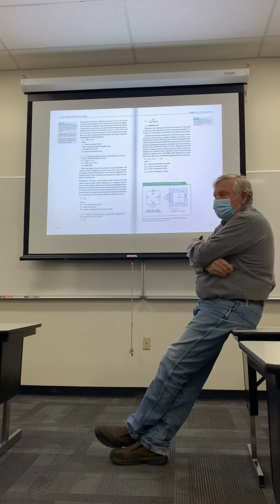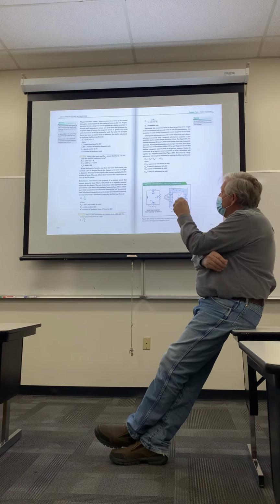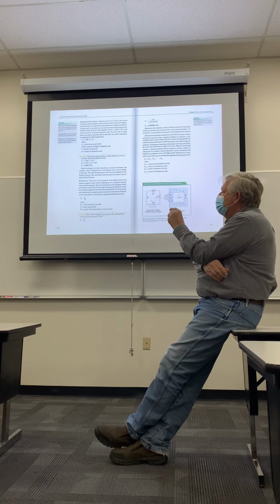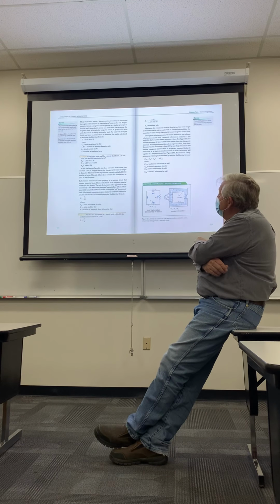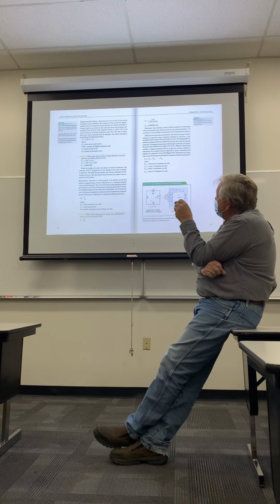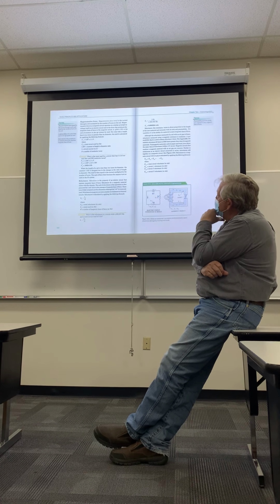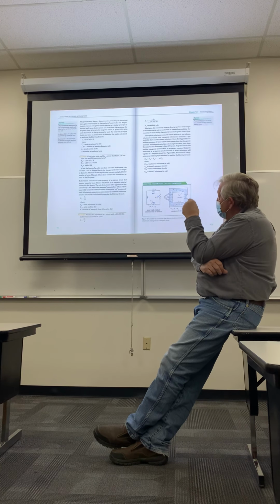But for the purposes of this class, I just want you to know that magnetomotive force is measured in Gilberts, right there, GB. It's a unit of measurement in the centimeter gram second system for MMF. So if you have a coil with a certain length, you multiply this constant 1.257 times the current, which is I, times the number of conductor turns, and you're going to get an answer in Gilberts.